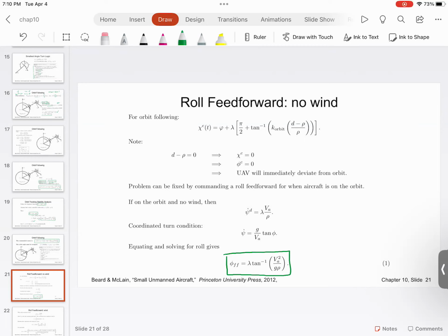When there is no wind, the course becomes yaw. Unfortunately, as we control yaw, because of the yaw to roll coupling, you are going to get some roll that may be undesired. So as you are tuning yaw, you will have to do the roll correction so that you have proper turning. So that's what all that means.